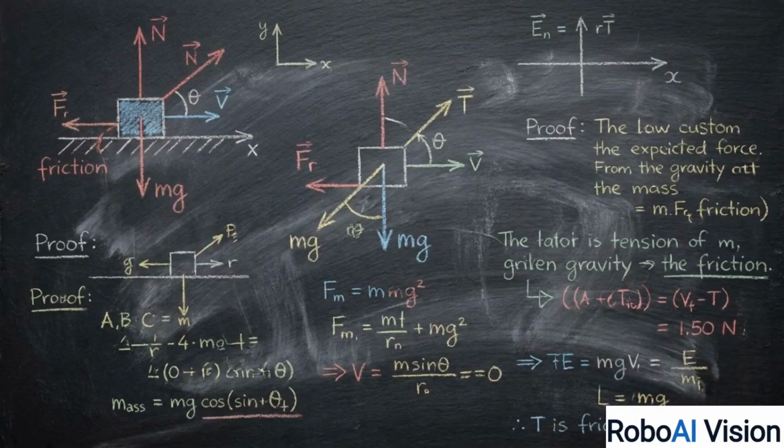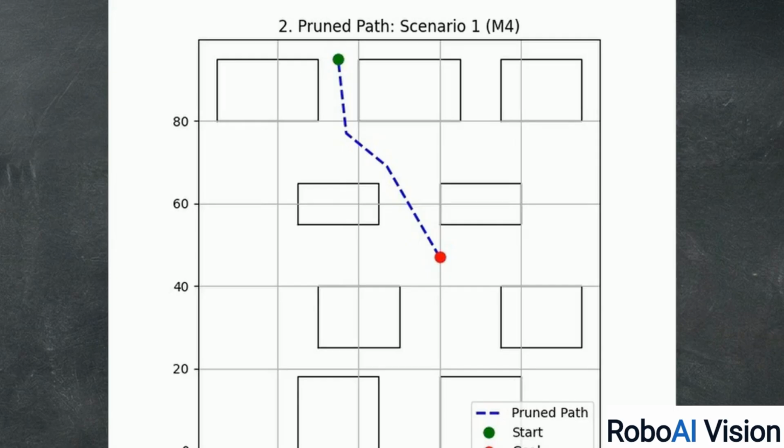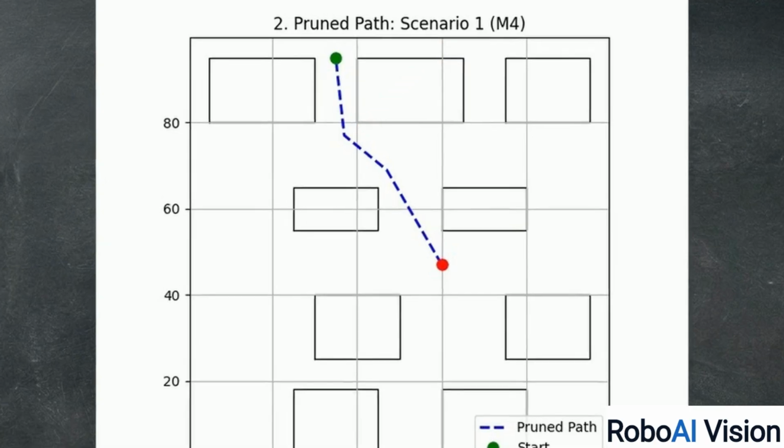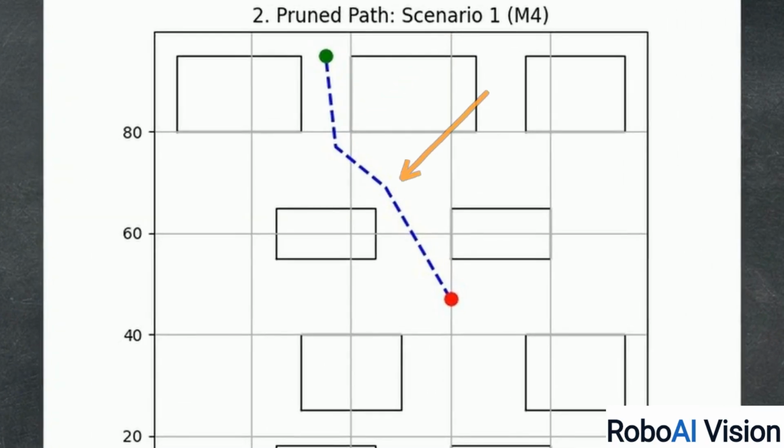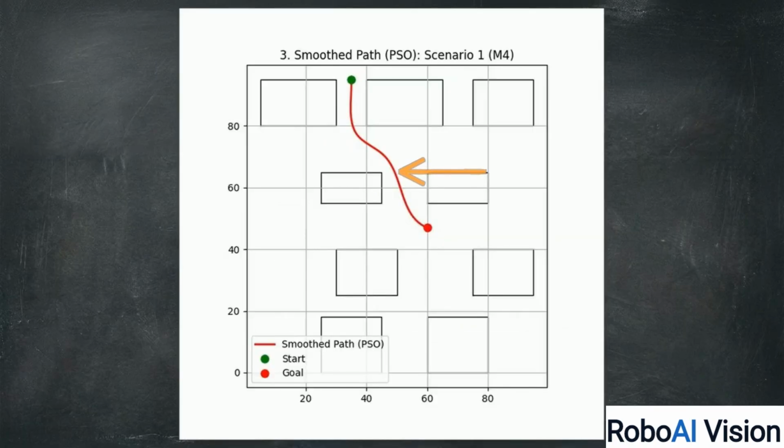We can now evaluate how this newly smoothed geometry dictates Newtonian physics constraints, specifically force, mass, and acceleration. This plot shows the unsmoothed line-of-sight path. The highest kinetic stress occurs directly at these sharp vertices. Without the spline applied, forcing a mass to decelerate to zero and immediately accelerate in a new direction maxes out the motor's impulse limits.